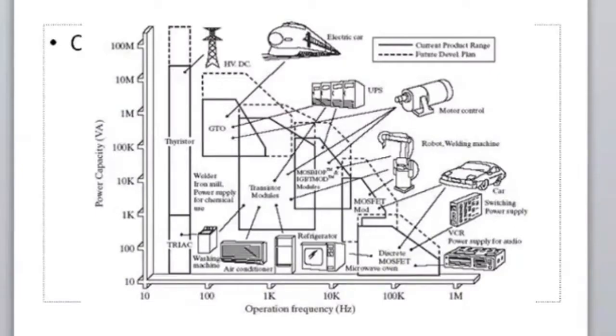When you tighten the belt, the current drawn from the supply will increase. It means that the load on the motor is increased. Right. In the case of fan load, how can you say that the load is increased or decreased? In the case of a fan type of load or pump type of load, I can say that the load is increased when the speed increases, because the load torque here, in the case of the laboratory, you will write as torque equal to 9.81 into R into S1 minus S2. I think you used this equation, right?